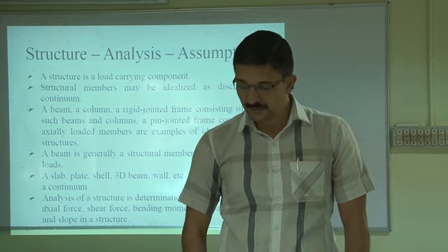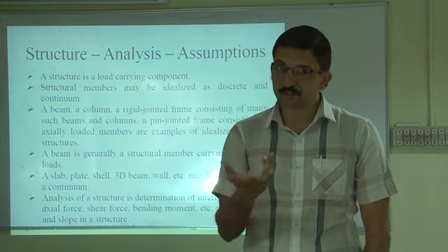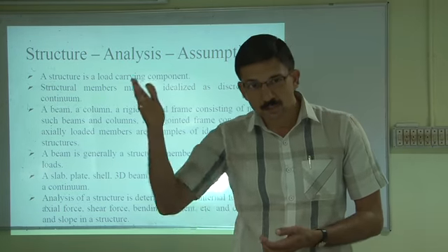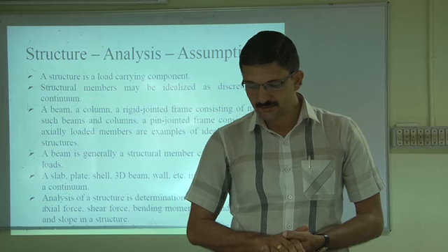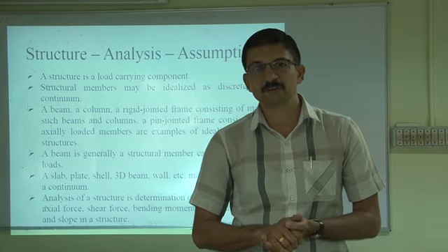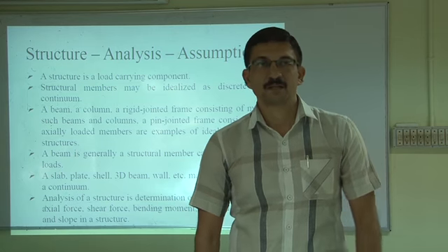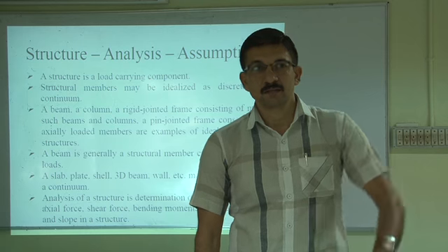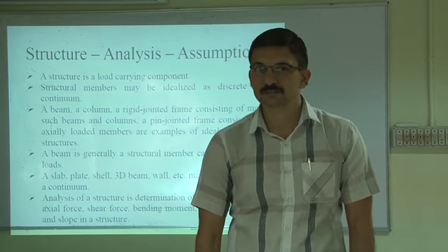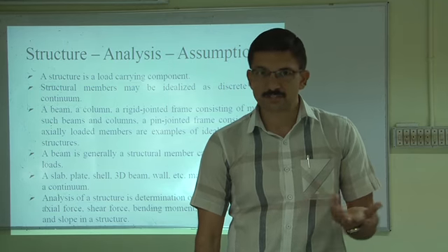Deflection, the internal forces are important to a structure, and when you design for serviceability criteria, the deflection has to be limited to a certain extent, and the slope has to be limited to a certain extent. So design codes are there which give limitations to deflection and slope also. For example, if you have a structure giving a deflection of say 1.5 meters in a building, in a room of height say 3 meters, it is going to affect the functionality of that building. So excessive deflection is going to be out of the question for a structure.